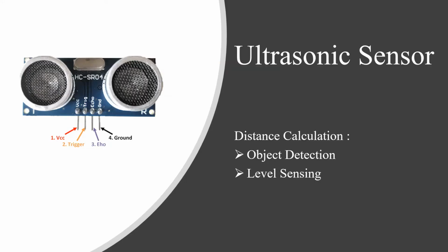Now coming to the hardware components. So firstly, we have the ultrasonic sensor. Now this ultrasonic sensor is the HC-SR04 module, which is a 4-pin module and has, of course, power and ground and trigger and echo pins, which uses high frequency signals so that they cannot be heard by humans. And this calculates the distance, and the range we have set for this is between 0 and 2 meters. So anything above that is out of its range.